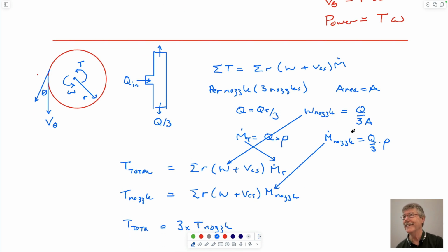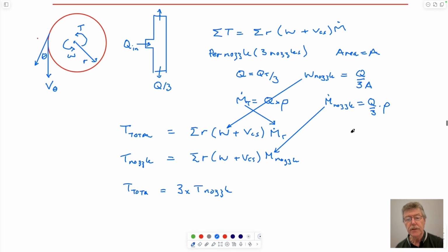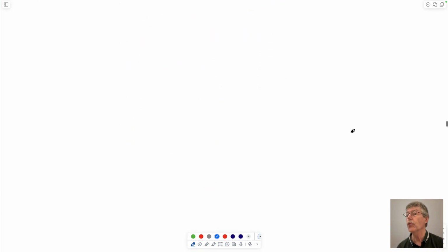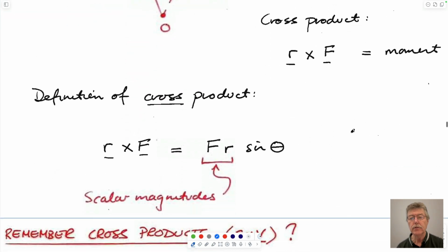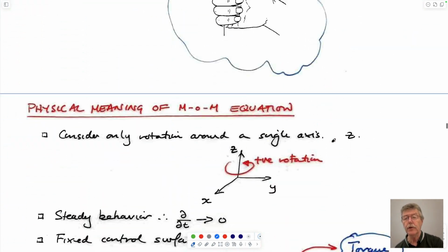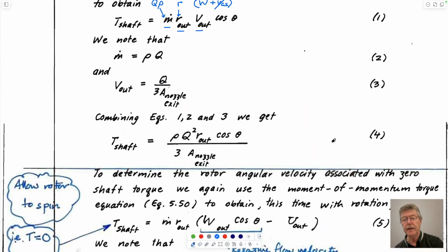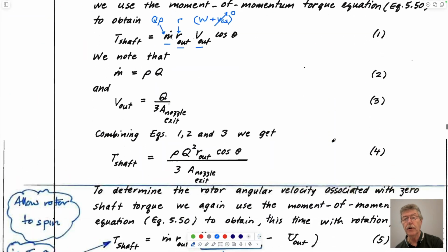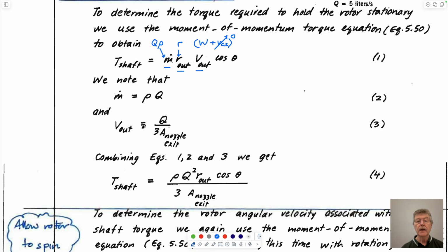Second question, just to be sure. So we're treating W as the out velocity, correct? W is the velocity out of the control volume, always. And so it also happens to be the flow rate in divided by the area of flow, which would be the volumetric flow rate. So these are the things we calculated for. It is in the denominator.